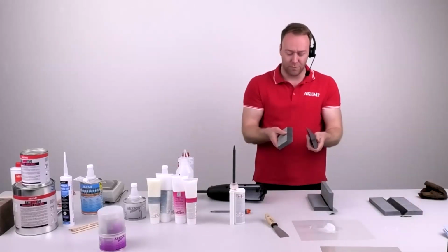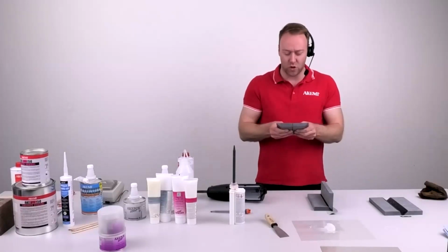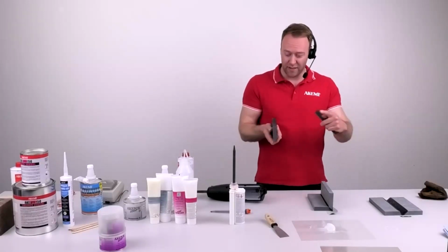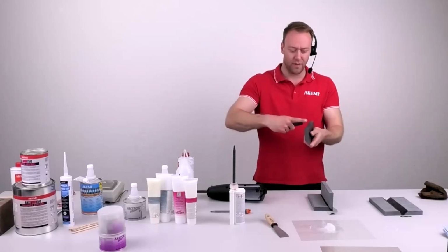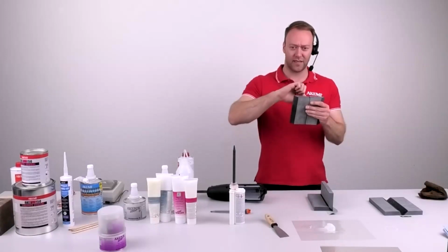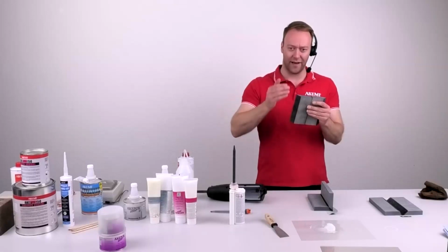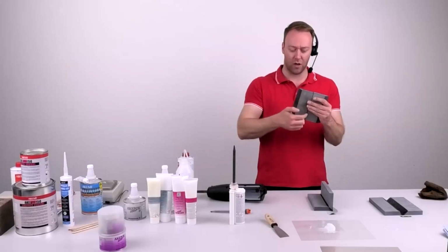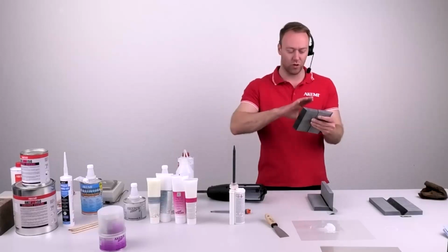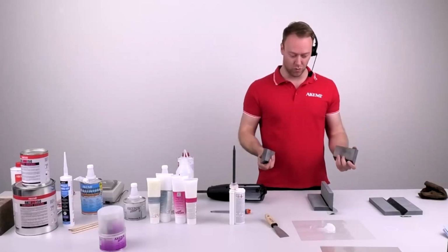When you have a normal bonding where you place just 2 stones together, the best thing is to apply glue on both sides and then press them together so that glue comes out on both sides in a homogeneous line. Not like here it's coming out and there nothing, then here it's coming out and nothing. I will show you a few pictures later. So that must be enough glue.